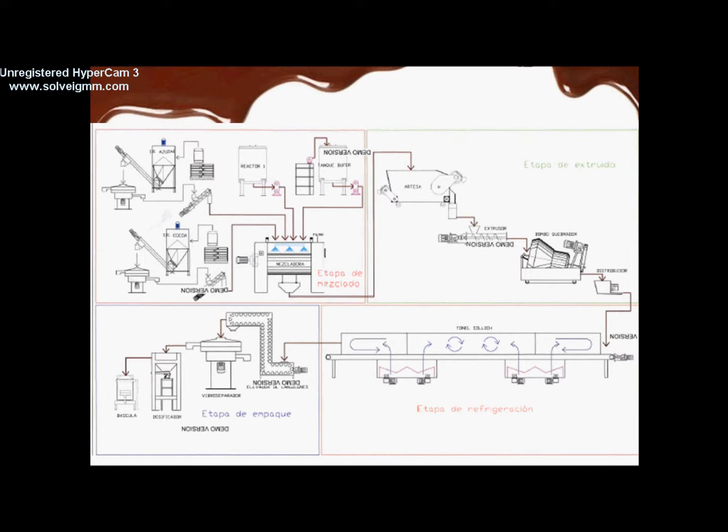Here the weighing of all powder and liquid ingredients is done automatically through load cells mounted on the mixer. Everything is controlled by a PLC in which the recipes for different products are set. The recipe controls the amount of each ingredient, the order in which they are added to the mixture, also the mixing times in each stage, and the temperatures of the process equipment. With this we can ensure our quality.